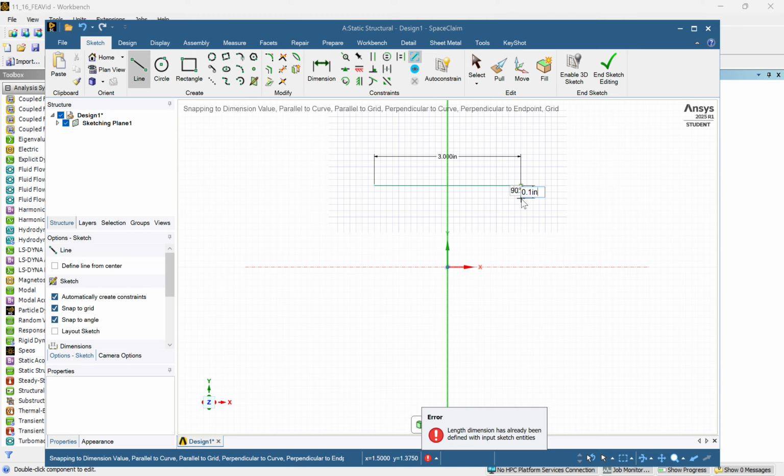We're going to give it a 0.1 inch thickness just because that's, at the end of the day, what our plies really come out to once they're all laid up. But yeah, we're going to go for that for right now. Our core is 0.25 inches thick, so we're just accounting for that here. And then our core is 2 inches tall.